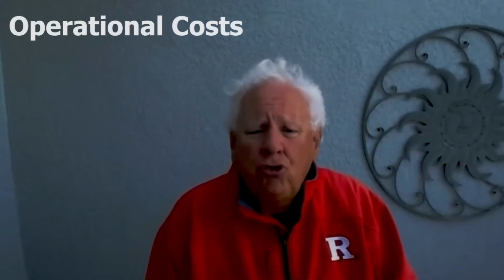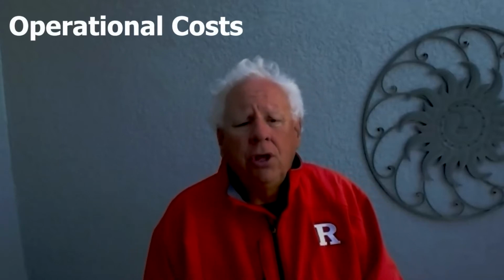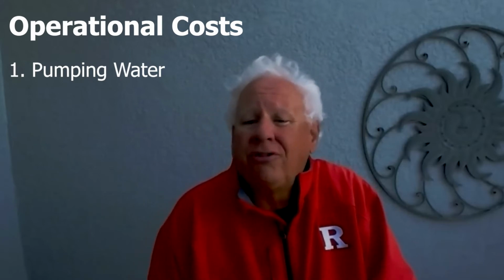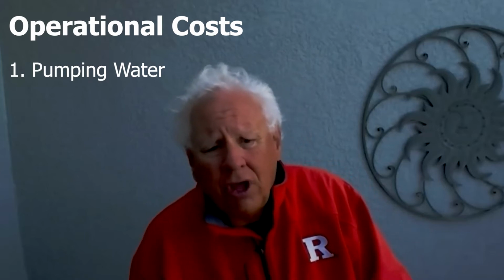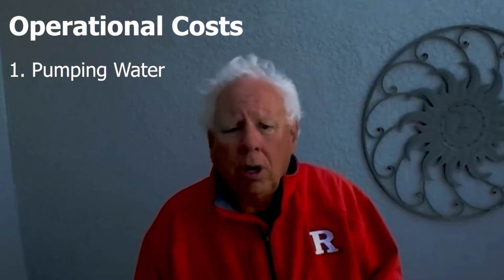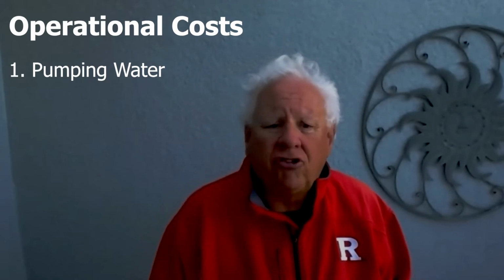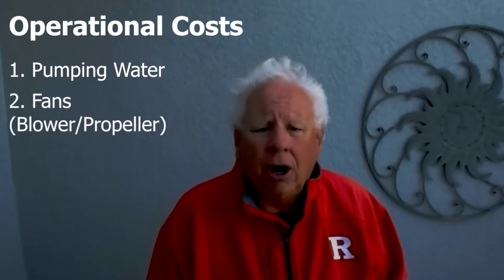The goal, as always, is to lower costs, and once we have a cooling tower, we must ask ourselves what energy costs we have added through operating. And there are two main costs to keep in mind. First, you must pump your water out to the cooling tower and back, so there's the cost of operating pumps. Secondly, within the cooling tower itself, where you're raining down the water and you're blowing air up through the water in order to get sensible heat change as well as evaporation, you need rather large fans to move the air.